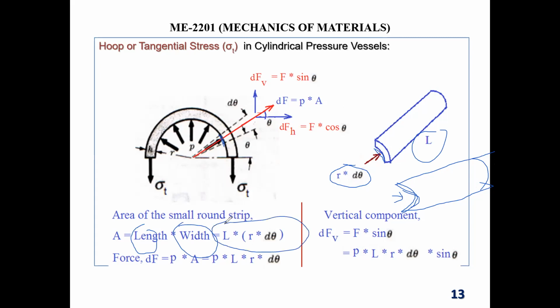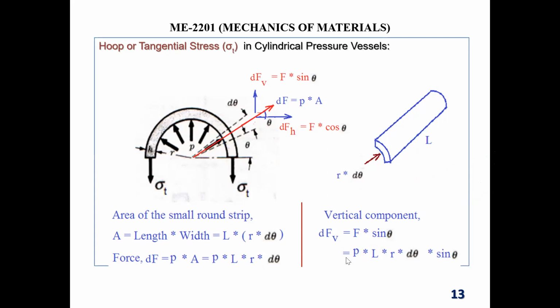If that is the area, then force is pressure into area. My pressure is P, so P into L r d theta. This is the force working right over here, dF. This is P into dA, and we got A as L r d theta.